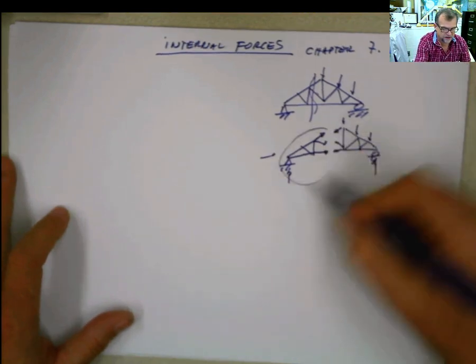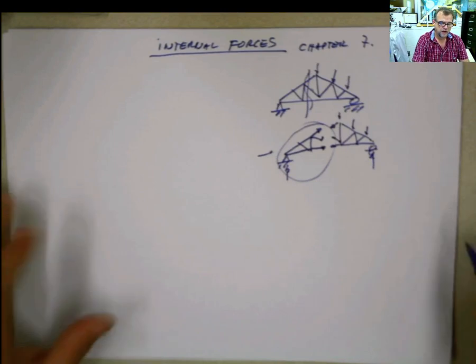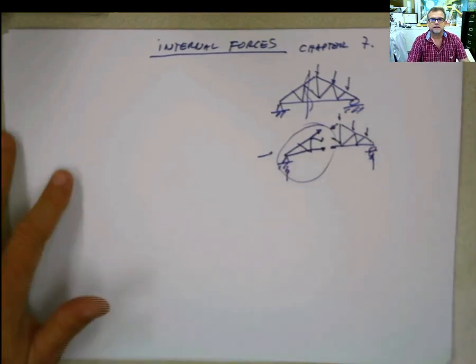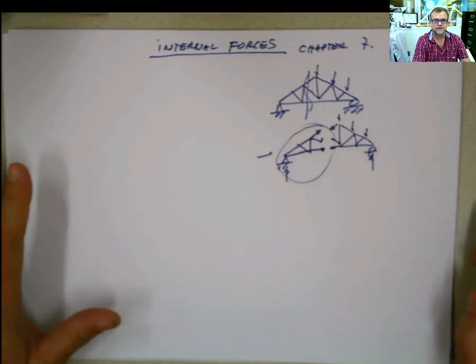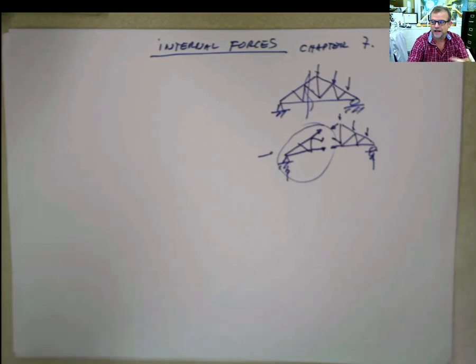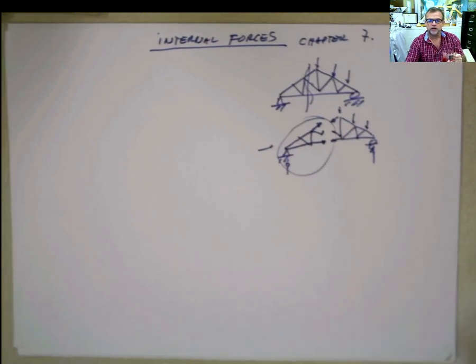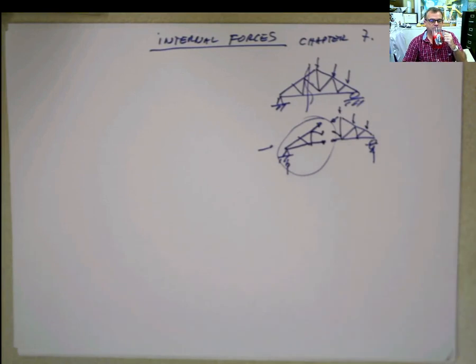And these forces are subject only to tension and compression. Yes, so you got that part. And those forces are how? Internal. Then yes, we discussed internal forces before. Those are internal forces that happen in the truss, also in the element. And with those internal forces, if we comply with all the assumptions and all the conditions that we have to keep, then those forces were only in tension and compression. That was chapter 6, and that was trusses.